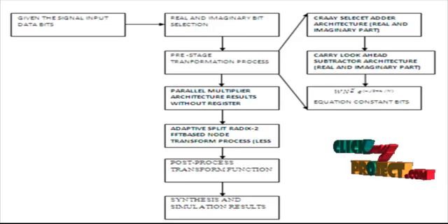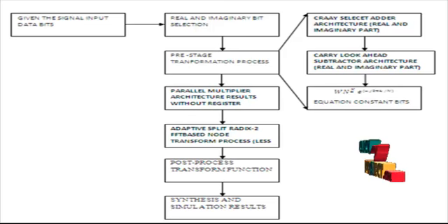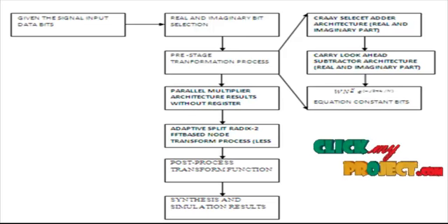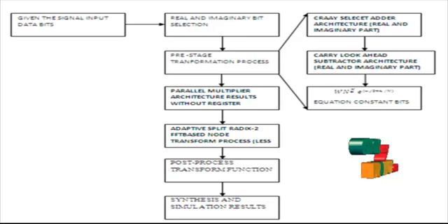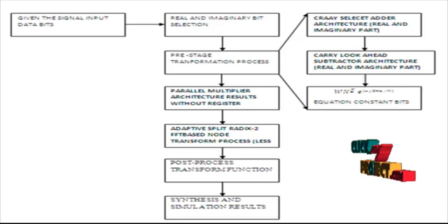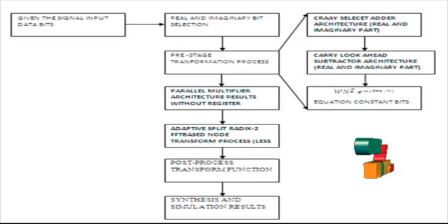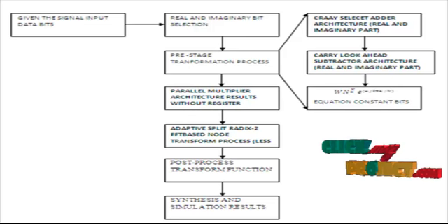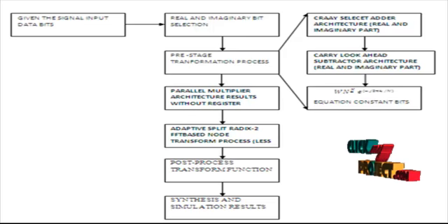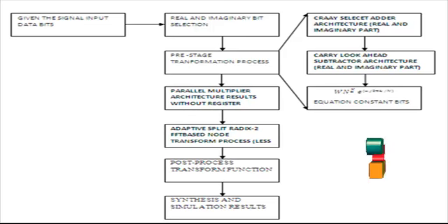The weighted equations are mainly based on the equation e power minus j2π nk by N. These equations are solved mathematically and all the values are calculated for the overall FFT architecture. Then we design the parallel multiplication architecture for our required weighted bit multiplication, for both real and complex processes. We represent the 3-bit level of adder, subtractor and multiplier. Adder means 4-bit, and likewise 4-bit subtractor and 4-bit multiplication, and in the same way 8-bit and 16-bit also.